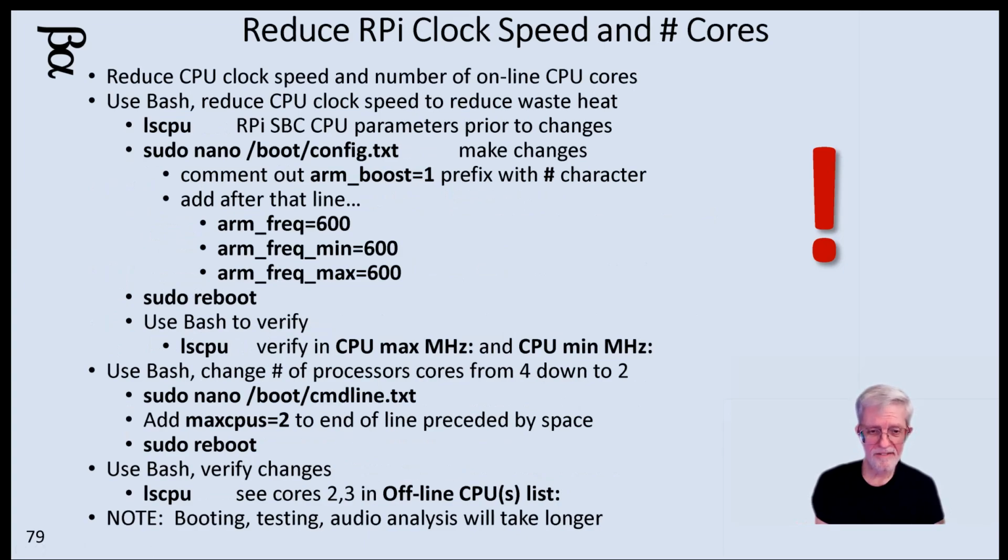You go in, you modify the configuration file, you turn off the speed boost, and then you set the clock, I didn't set it to 800 megahertz, I set it to 600 megahertz, correction there. And then you reboot it and you verify it.